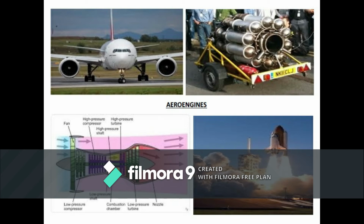This type of engine allows us to increase the temperature, whereas in a normal turbojet, turbofan or turboshaft engine, we cannot keep on increasing the temperature in the combustion chamber because of the material limitations of the turbine and other components. As these are missing in ramjet and scramjet, we can very well utilize it to increase the temperature. So this type of engine is used along with other turbojet engines. When the fighter aircraft starts flying at supersonic speed, more than 1 Mach, then the ramjet and scramjet engine is utilized.